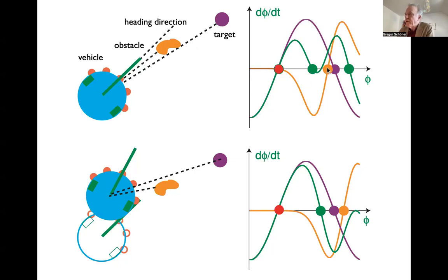You see, this attractor is actually a little bit to the left of that direction, so the heading is being repelled a little bit from that. And in the next moment in time, a couple of steps later, the vehicle's position was like that. So it's now heading further to the left, so to the left on these plots. And in this position, it has also moved forward. In this position, the bearing of the target is now closer to the current vehicle's heading than the bearing of the obstacle. See here, this attractor moves through the bearing of the obstacle, so it's flipped around.